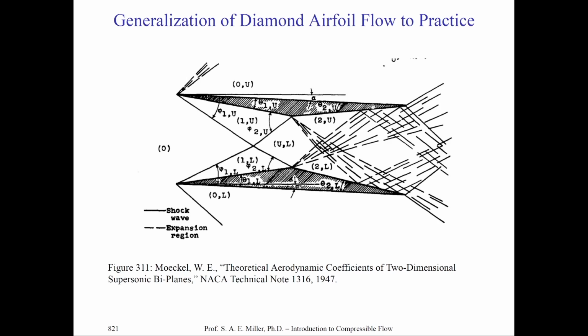Now, along the straight walls, the expansion waves will come along and bounce off the walls as additional expansion waves. Indeed, the expansion waves create that cross net, which we can analyze with method of characteristics, which we'll learn later in this class. You can see in this particular case, this acts as indeed a compressor, which is the inlet and convergence section, and the divergence section, a kind of nozzle where the flow is expanding. And so we've taken the diamond airfoil, cut it in two, and created a converging divergent nozzle.